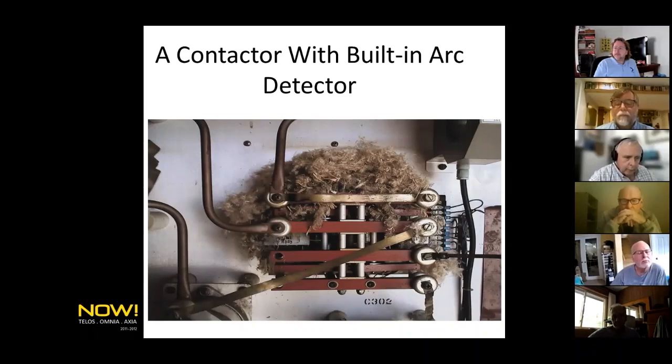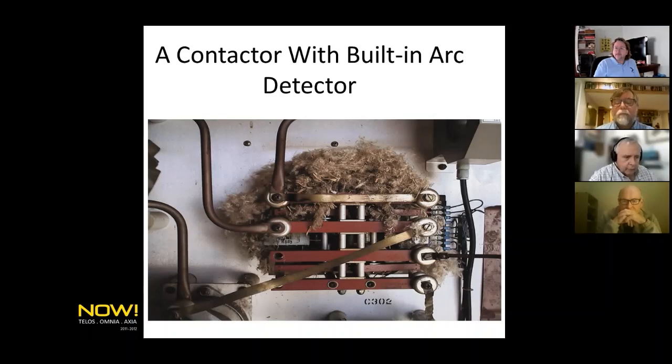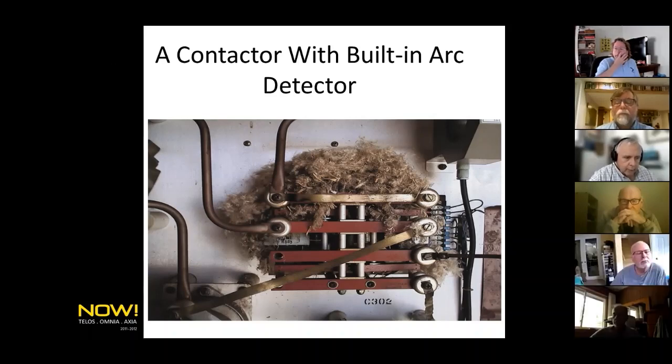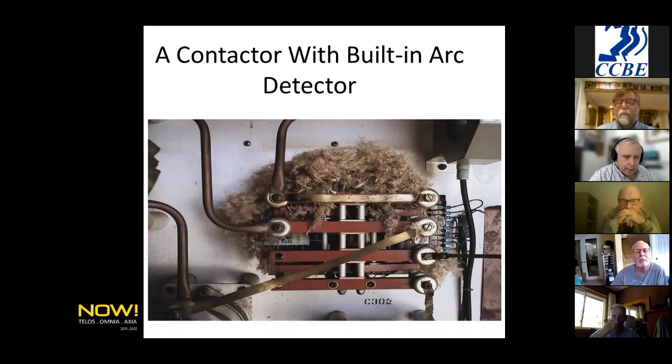This was a site we had cleaned out. And the very next day, the manager of the station called me up, just raising Cain with me about how he paid for me to come and do this work, and I didn't do anything. I went down and opened up the door, and doggone it if those mice hadn't just completely rebuilt their nest again. So we started looking a little closer. We found there was a crack at the bottom of the ATU that allowed the mice in. Once we sealed that up, the problem was solved.